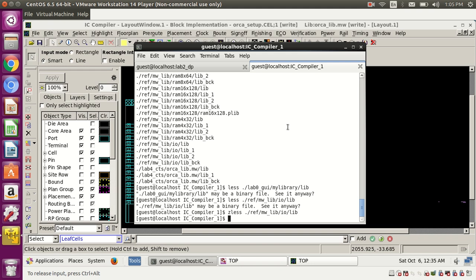So now the clock will not go directly; the clock will go through this cell. This cell will not give the clock directly; it gives it based on an enable signal. Whenever the data is going to be stable, the tool will generate one enable signal and give it to that special cell. So whenever it is enabled, until it is de-enabled, that is, goes from 1 to 0, it will not give the clock to the register.